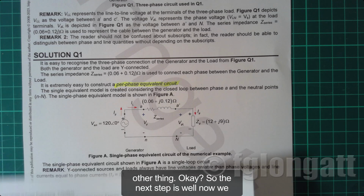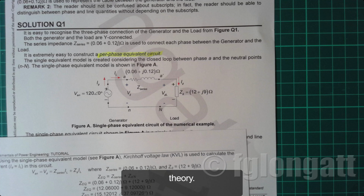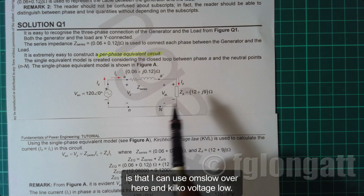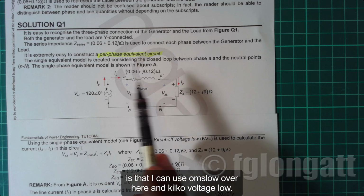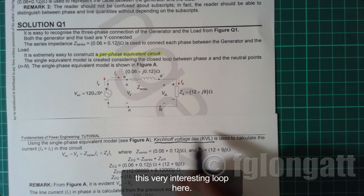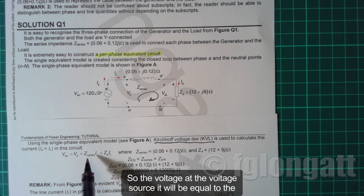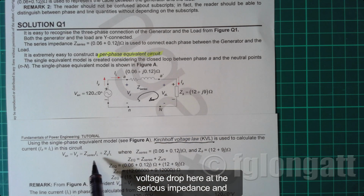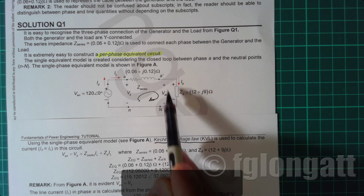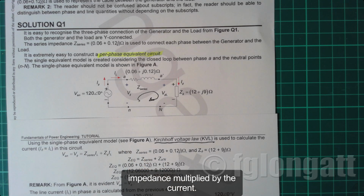So the next step is, well, now we have a circuit. Now you can apply everything that you know about circuit theory. The interesting part over here is that I can use Ohm's law and Kirchhoff voltage law. If I use Kirchhoff voltage law in this very interesting loop here, the voltage at the voltage source will be equal to the voltage drop at the series impedance, and using Ohm's law, that is the series impedance multiplied by the current, plus the voltage drop through this load, and this is the load impedance multiplied by the current.